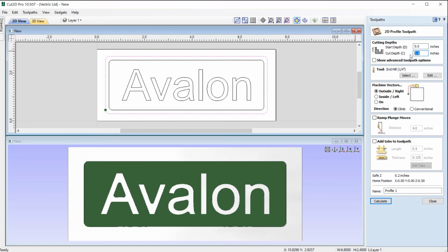So I'm going to type in Z followed by the equals key, and that's going to enter that parameter from our material settings. So whatever our Z value is within the material setup, it's going to apply that here when we press Z equals, or we could simply have just typed in 0.25 within this box here.